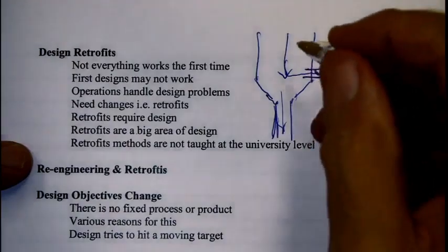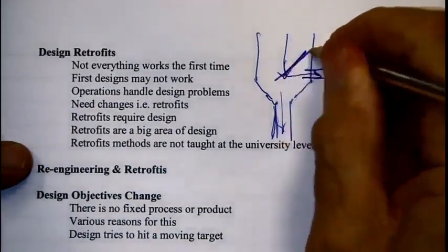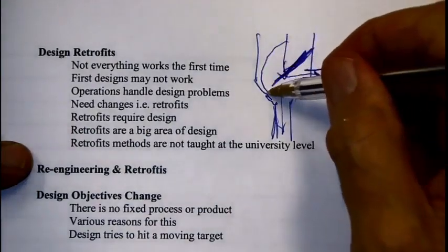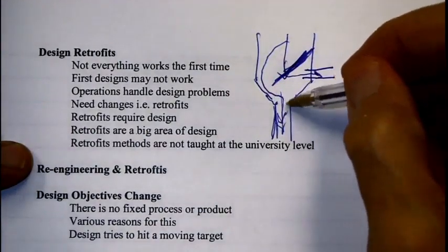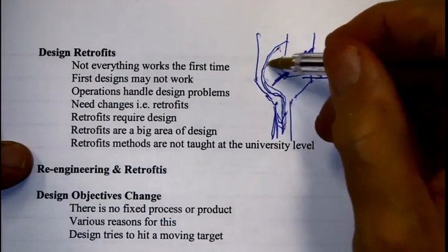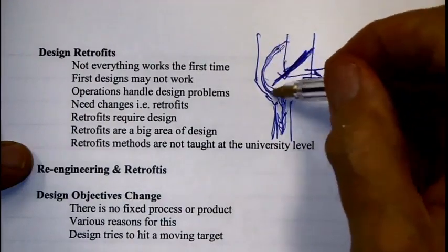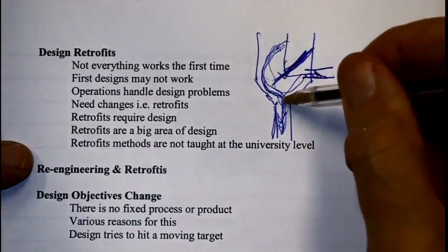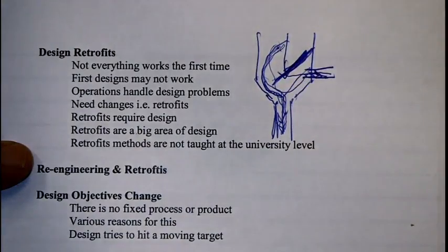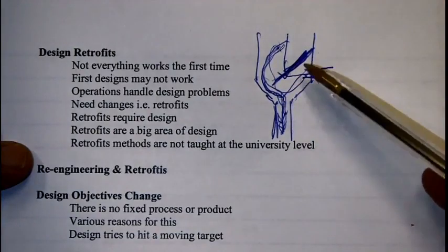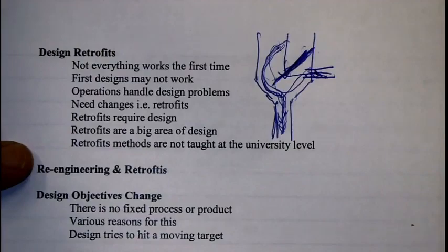The idea, though, you come in and you put a baffle right here, baffle plate right here. So the particles have to go this direction. So there's an increase in the larger, coarser particles, and the finer particles have to flow around this baffle and out. So you have a better separation of large versus fines than you did when it was open.